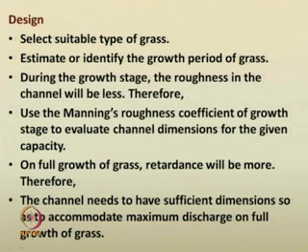What are the various design procedures? Unlike the earlier methods of tractive force or permissible velocity, we will not be going deep into the design of grass channels. Just to give you an overview of the procedure, we will discuss it here. You have to select a suitable type of grass, and you estimate or identify the growth period of the grass.